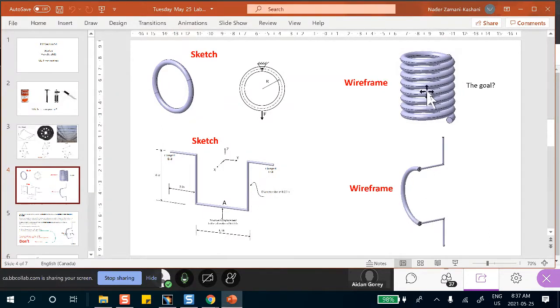Here it's also true, but it becomes kind of iffy. If you want stresses, then obviously you can't use beams. And if you want stresses for springs like that, then you have to do it with solid elements. But if that is not the case, you should do these things with beam elements. There is a major point deduction if you try to do these things with solid elements.